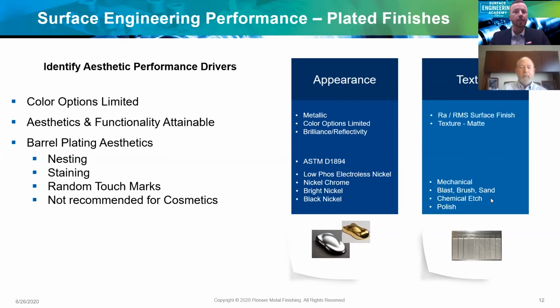It's also important to note there's very limited color options available for plated finishes. Of course, there's black applications, black zinc, black nickel, black chrome, but it's very common with those as well because platings are barrier coatings by and large, and so there's really not a good adhesion surface or roughened surface for those particular, typically organic colorants to adhere to.